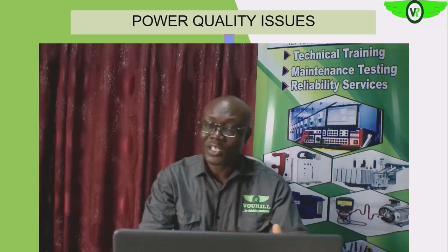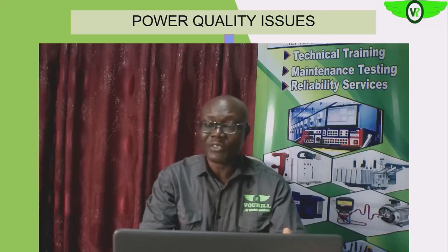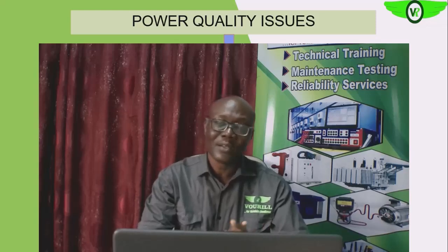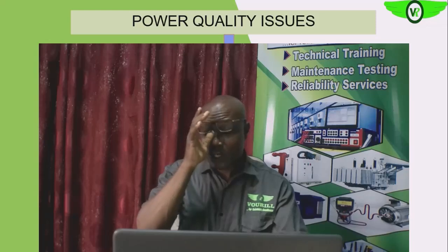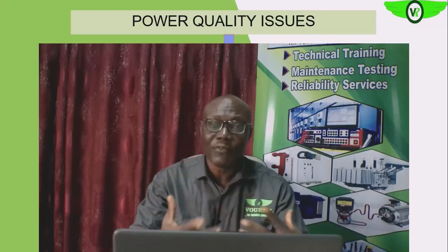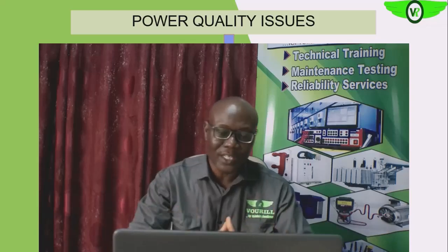So that is why under voltage is not good for our system, because it will increase the heating level of the electric motor, reduce the insulation capability, destroy the electric motor insulation, and cause winding burnout. Are we getting it? Especially if the under voltage is sustained for a very long time, or it is repeated over a period of time.